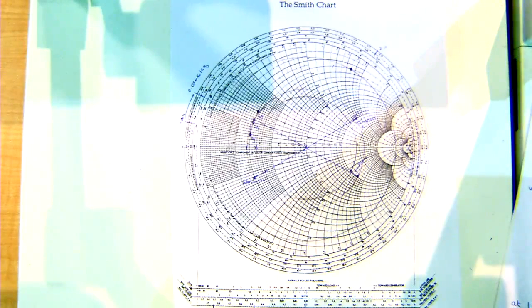As a general rule of thumb, as your length of transmission line becomes larger, your match over frequency gets worse, because it's now a larger number of wavelengths incorrect. So usually you try to build everything with the smallest lengths of coaxial cable or whatever when you're doing these matching networks.